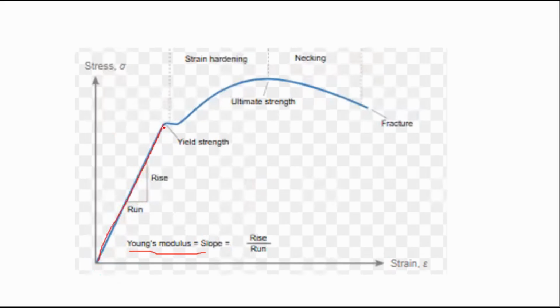And then as it reaches a point somewhere below here, it is the elastic limit, below the yield strength. After the yield strength or the yield point, the material will no longer elongate proportionally to the stress applied to it. And then it will go to its maximum capacity, or its ultimate tensile strength, right here before it ruptures at its rupture point.